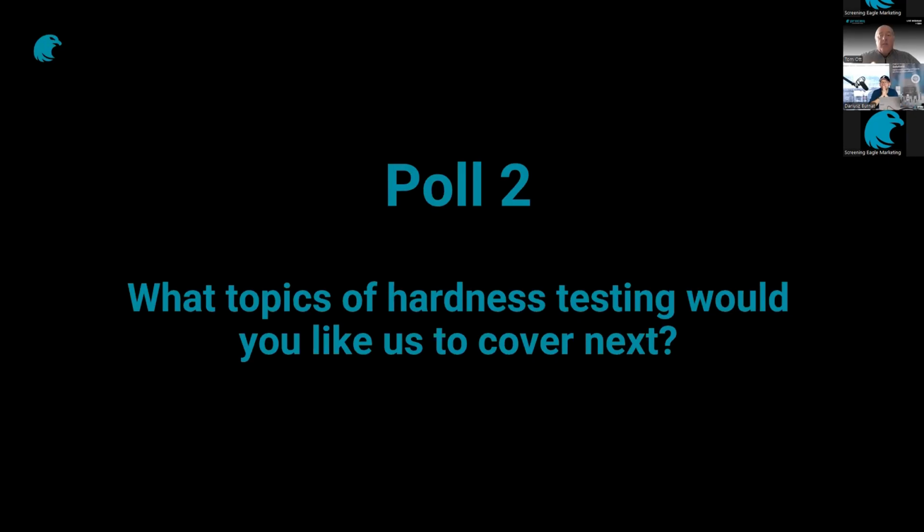Even though we do have support foot adapters for measuring on cylindrical objects with the Equotip Portable Rockwell, that is a less preferred method because of the size of the probe support and generally the restricted nature of boiler and superheater tube walls. The UCI probe is going to offer you much better accessibility and, because of that, reliability and repeatability.